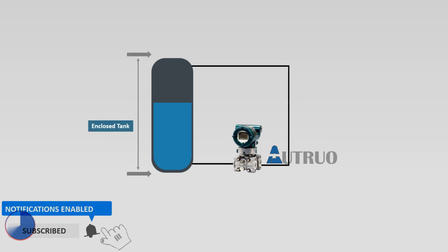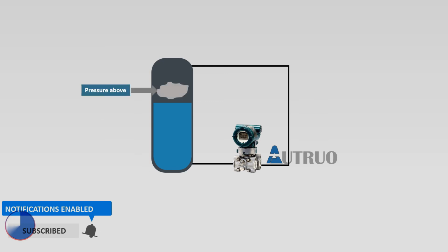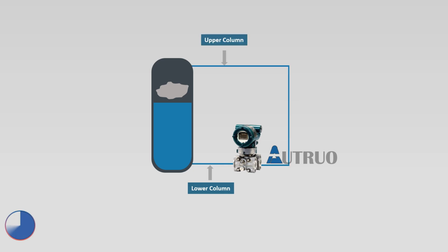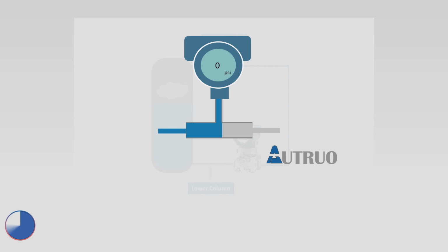In a closed tank, the atmospheric pressure is of little consequence for level measurements. The transmitter measures the pressure within the liquid column and liquid head. Values are transmitted to the transmitter via the oil-filled capillary lines, or through a pair of sensor modules connected via interconnected cables. The transmitter calculates the difference between the two capillaries or the sensor modules.